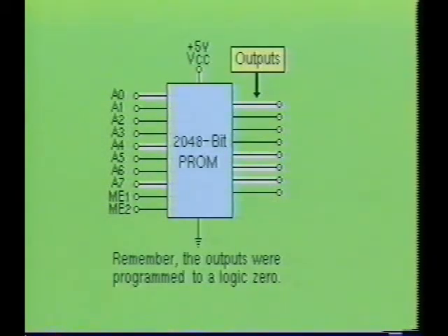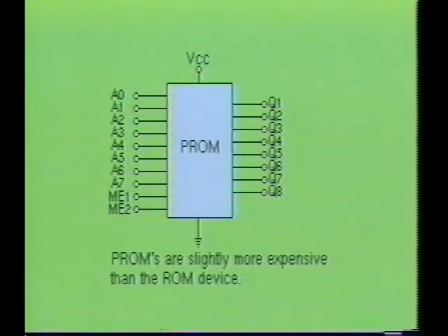To verify that the PROM device has been programmed, apply a logic 0 to both of the enable inputs, then check for a low output at the desired address. Programmable read-only memory devices are slightly more expensive than ROM devices, but their flexibility often justifies the higher cost.